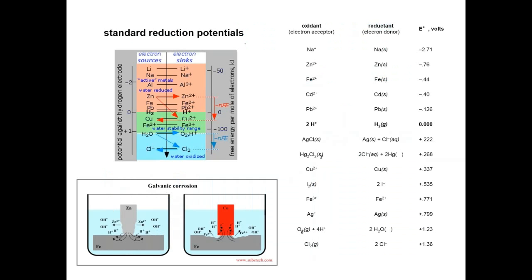Let's say in this table, where the standard potential is that of a hydrogen gas proton, you can see the rank of iron being minus 0.44 volts, so that's the electrochemical standard potential as compared to hydrogen. However, zinc, which is used for anodic mitigation or replacement, corrodes more than iron, as zinc is a good sacrificial anode for iron. On the other hand, down the list you will see copper, silver, or even noble metals having better resistance to oxidation compared to iron.